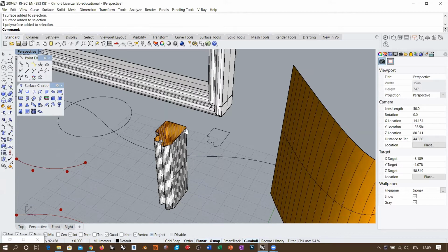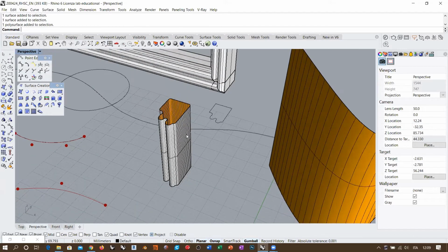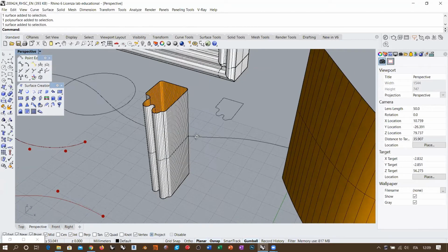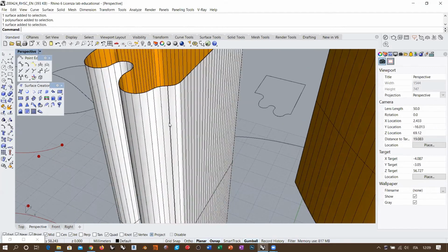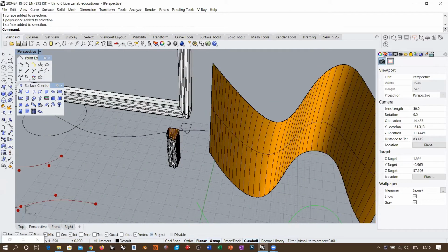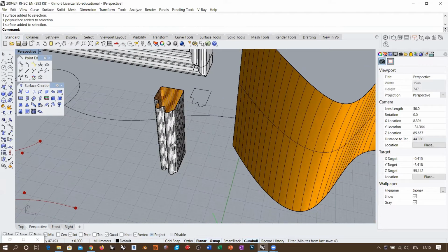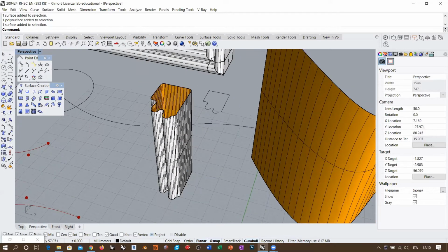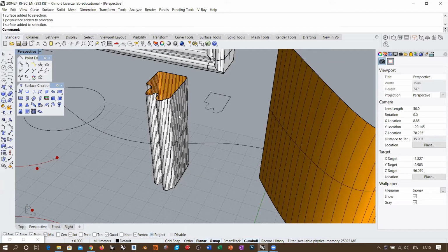One other consideration that you might want to have for this surface here is that you see that the seam, which is this internal edge, is basically happening here on the front of your curve and surface as well. Eventually, this is a detail that we don't want to have visible, even if it doesn't matter in terms of visualization, like rendering and so on.